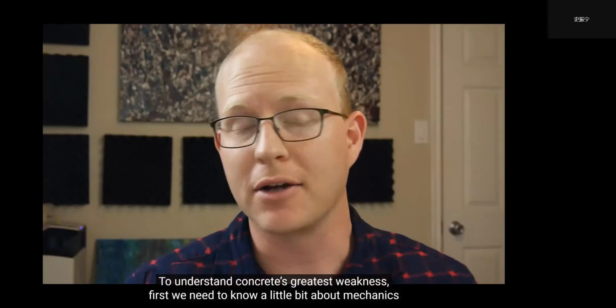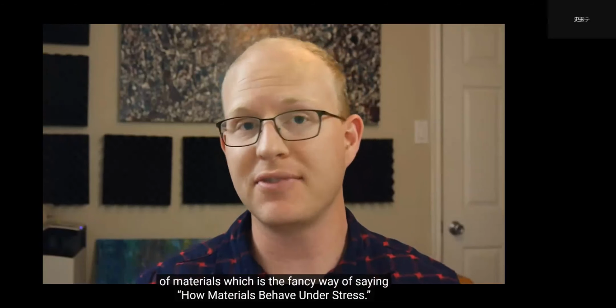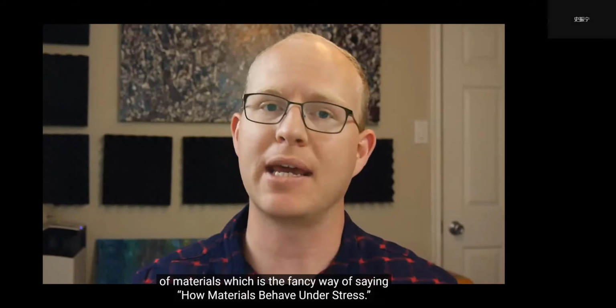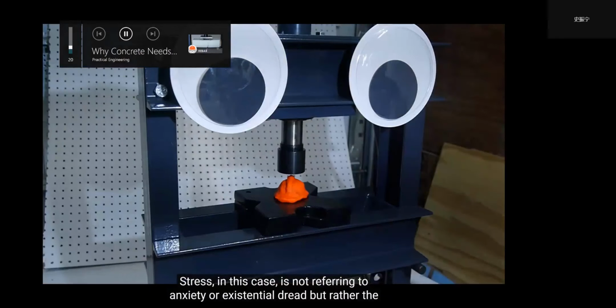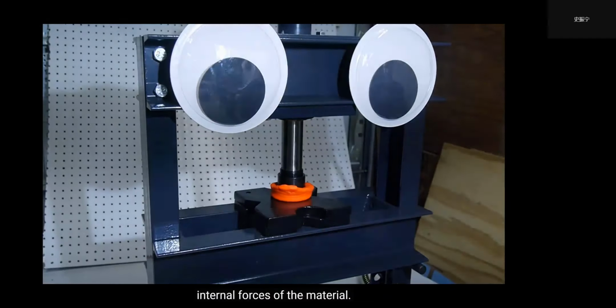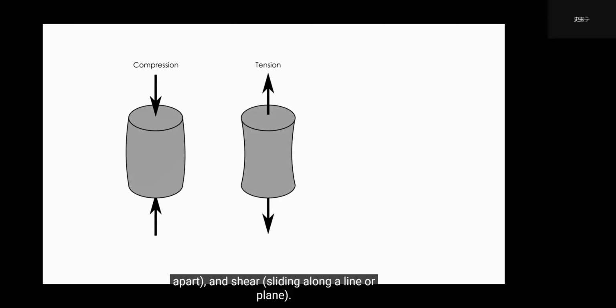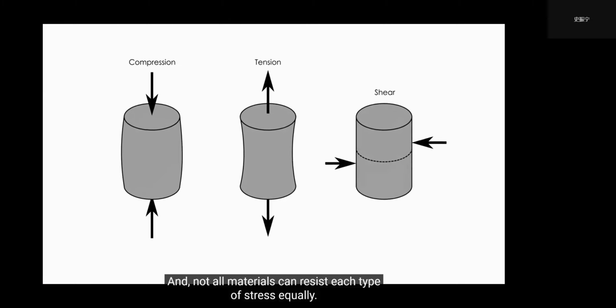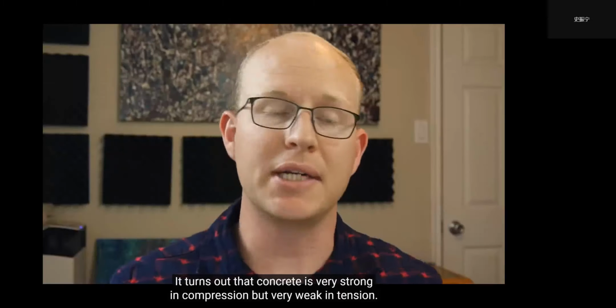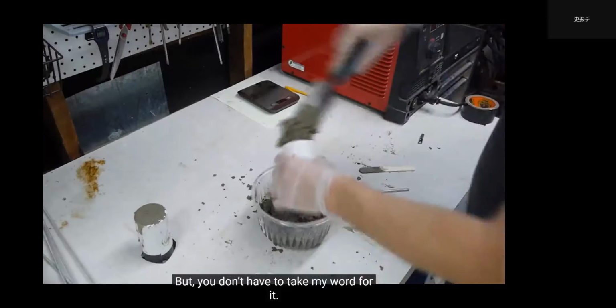To understand concrete's greatest weakness, first we need to know a little bit about mechanics of materials, which is the fancy way of saying how materials behave under stress. Stress in this case is not referring to anxiety or existential dread, but rather the internal forces of the material. There are 3 fundamental types of stress: compression, pushing together; tension, pulling apart; and shear, sliding along a line or plane. And not all materials can resist each type of stress equally. It turns out that concrete is very strong in compression and weak in tension. But you don't have to take my word for it.